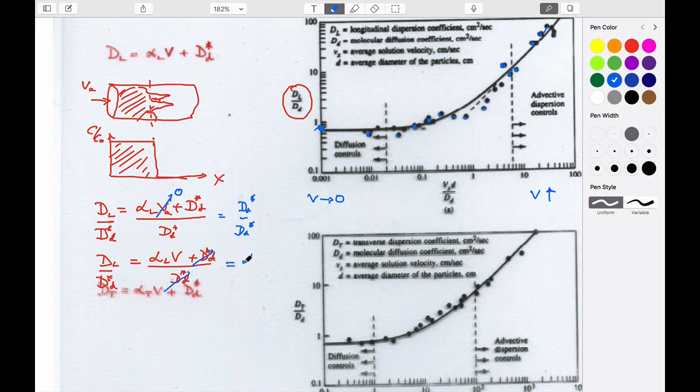So this will end up being alpha times advective velocity. So this is a coefficient, and this is the velocity that you're flowing things at. These are the velocities. They're plotted in a slightly different way, but you'd expect that this curve, this gradient here, is something that reflects it. So you increase the velocity by 10 times, and if this changes by 1 cycle, this also changes by 1 cycle. So this gradient here is 1 cycle by 1 cycle. And so physically what this means is at very low flow velocities, diffusion's only acting.